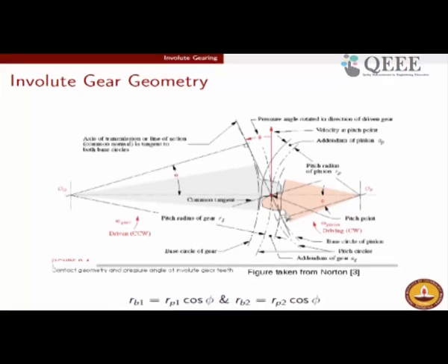Fortunately for involute gearing, the common normal does not change during the course of engagement. From the perspective of transmission of forces, the normal force is the major force which is getting transmitted even if there is no friction in this process. That is why it is called a positive drive. It does not depend upon any friction aspects for this mechanism to work. It does not work on the no slip condition principles.